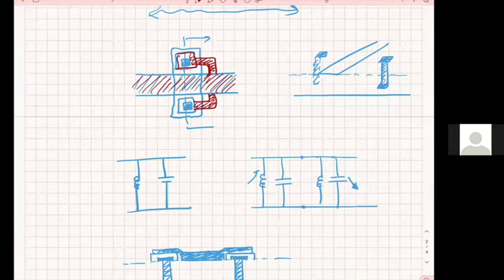Now, we are not going to do this. MATLAB cannot do this for you. My only advice to you is for a very small shunt inductor and very large shunt capacitor, you assume they are lumped elements. When you have a lumped element, in MATLAB, you introduce it as a lumped element, as an L and C, not as a section of line. And then if you have to go to the lab and materialize it, that's how I would do it. So that's how I would do my design in this particular case.